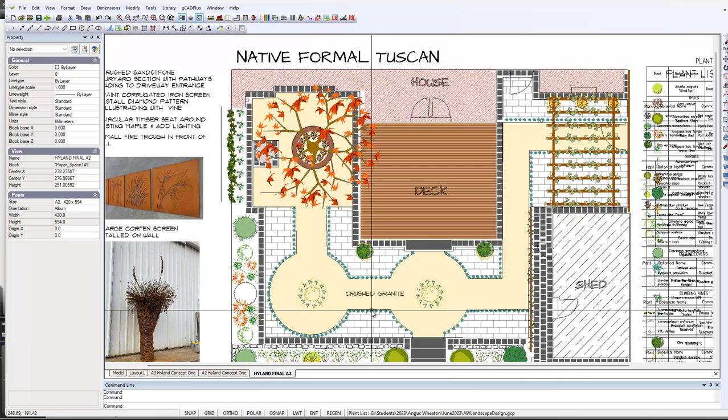So it's a long-winded way of showing this, and it would be far better, of course, to start your polyline over here, work around there, go into arc mode, back into line mode, arc mode, line, come around here and do it all in one go. But you can manage it and clean it up, and that's best done by isolating the two polylines, exploding them, selecting them all and joining them.